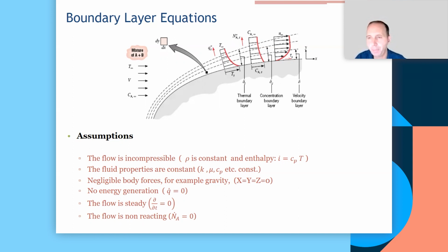So what is a boundary layer equation? It's the governing equations for flow over a lightly or slightly curved surface. And what is a slightly curved surface? It's a general concept, or a reasonably loose concept, but it's an important one. If you are looking at what you see in front of you there, you can easily guess, I think, that this dashed line represents the path taken by the particle on average. Perhaps it's turbulent and fluctuates about it, but by and large, the particle follows reasonably well the contour of the surface.